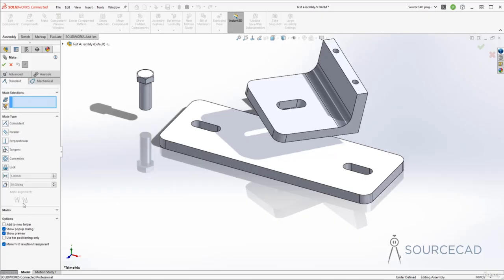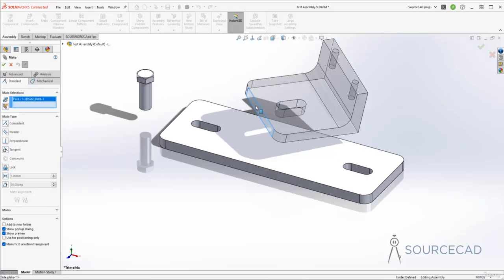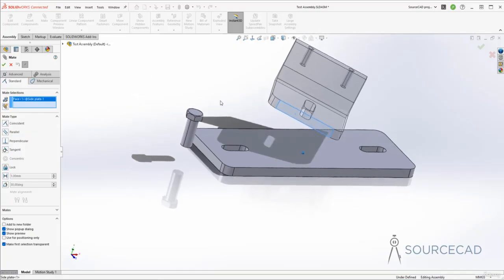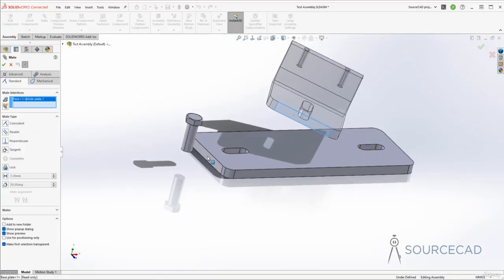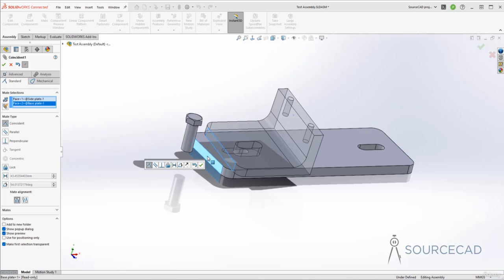So with these default settings, let's start with this face. So I'll select this face, and as you can see now this turned transparent, and now we can just select all the other components. So after selecting that, just orbit your drawing and select another face. Now in this case, you don't need to control select it. And as I selected these two faces, automatically it will show this kind of pop-up dialog box. And all of these mates are exactly the same mates that we have here. So the same mate will show up here. You can select from here or here. It's exactly the same thing.